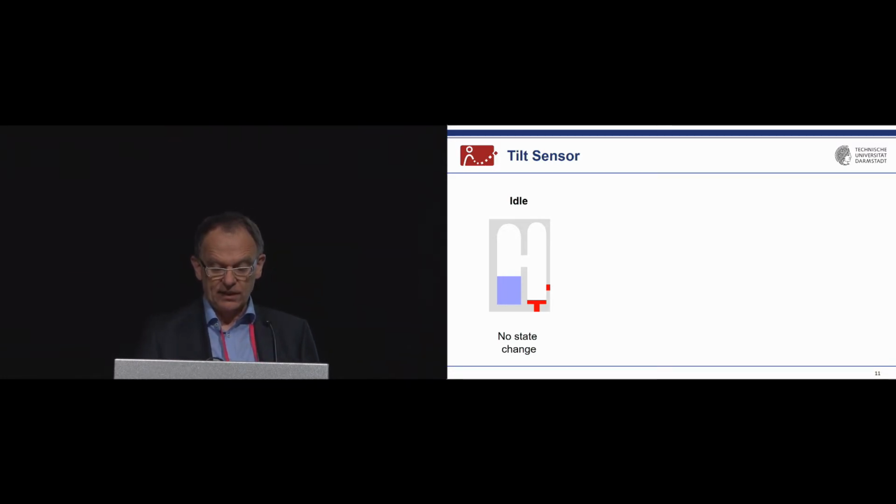First, looking at the tilt sensor, of a specific kind of tilt sensor, you have to custom design it for your purpose. In this case, we just want to detect even if it is just tilt by 90 degrees once. So in this cut-through, we see two chambers, one with the liquid and the other one with the two conductive areas, as explained. That's the parts in red.